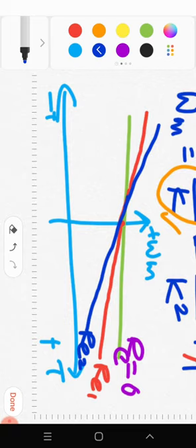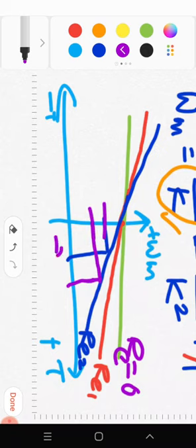So on motoring side, as well as on braking side, as slope is increased, a small change in the torque will result in a large change in the speed. So this is the change in the torque, and here is the change in the speed.